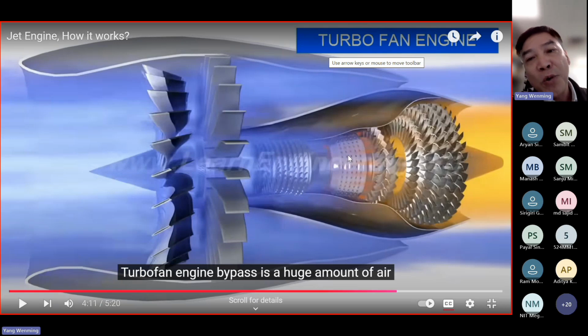So the fourth one is the combustion chamber. This one is the combustion chamber. Basically the jet fuel will be injected into this combustion chamber and burnt inside, thereby increasing the temperature of the combustion products significantly, for example, from 450 degrees C to more than 1,700 degrees C.